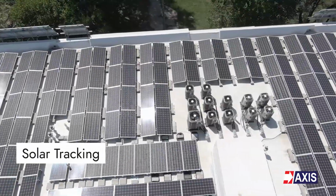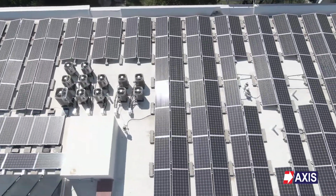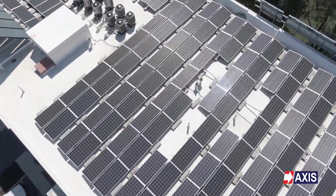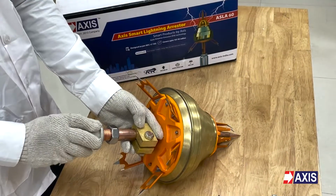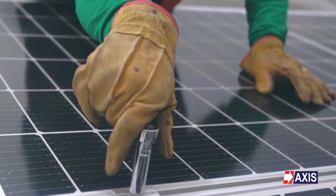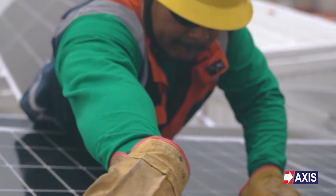Secondly, solar tracking. Modern solar farms include tracking, which makes the PV modules move along with the movement of the sun. The designer needs to be aware of this movement and make sure that the modules are protected throughout the day regardless of their position. Thirdly, shadows. The efficiency of a solar plant can be affected if the lightning protection system, especially the lightning arrestors, cast a shadow on the modules. Thus, the designer should make sure that they minimize the impact of shadows on the PV system.